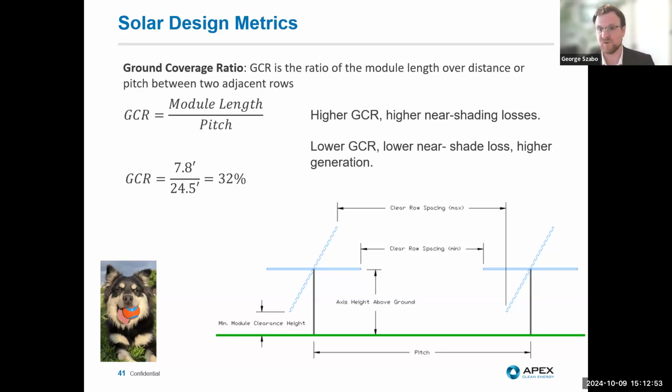But one, it's not going to be ideal for the plants to have that obstruction. And then two, we don't want the lower edge of our modules shaded due to that vegetation. So with agrivoltaics, it might be considered to add a little bit of additional length onto the piles themselves. The piles being the foundation piece that holds the rack together to elevate the entire rack up higher.